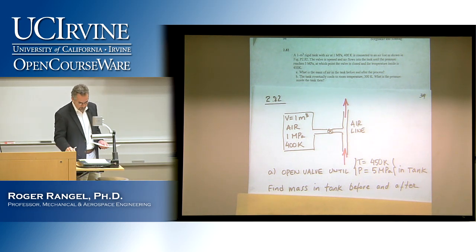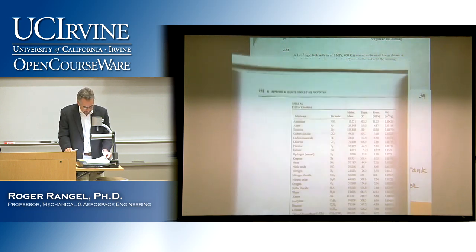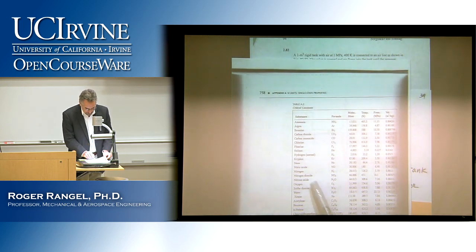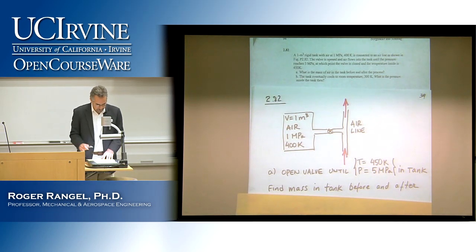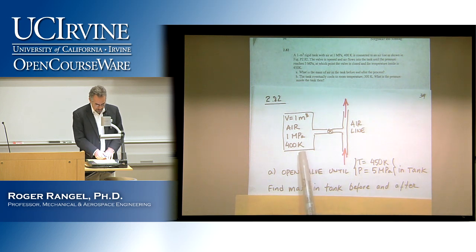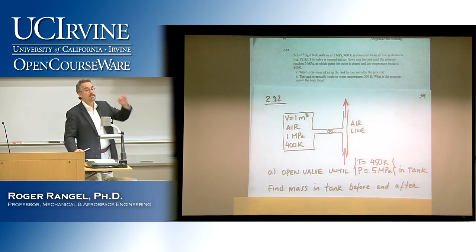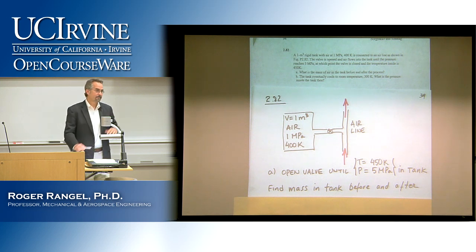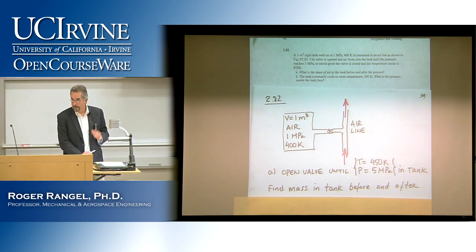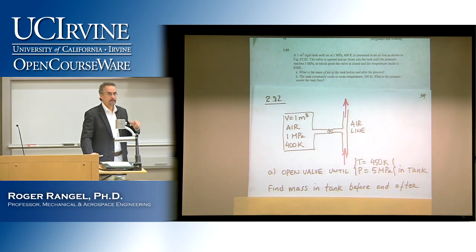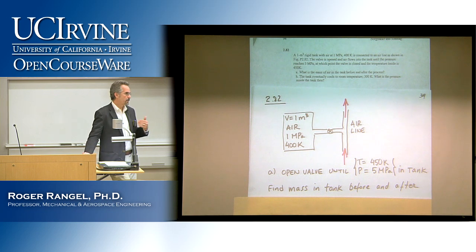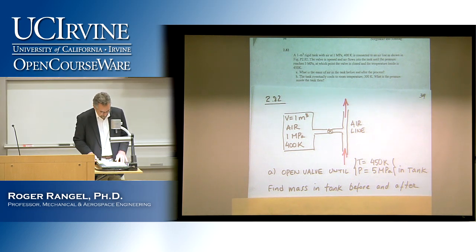But then we check the temperature. And the critical temperature, what did I say, was 126 Kelvin. And what is my temperature? Is initially 400 Kelvin, then goes up to 450, and then it will cool down to 300. But I'm always above the critical temperature, at least around 3 times, if not more. So that seemed to be okay. So I can probably use the ideal gas law. And so that's the reasoning when you're doing a problem like this.